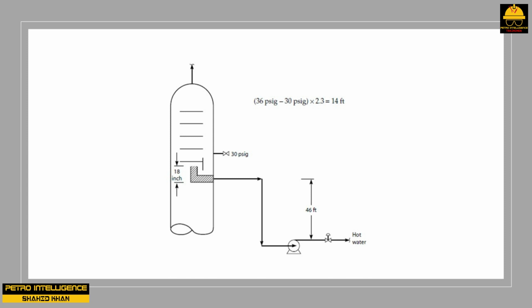But it still seems as if I am missing at least half of the 46 feet of liquid head to the pump. Where is it? Well, dear gentlemen, it no longer exists. Picture illustrates the true situation. Let's say we are pumping 110 GPM from the pump discharge. But only 109 GPM can drain through the draw-off nozzle.